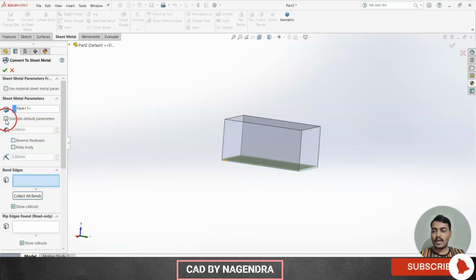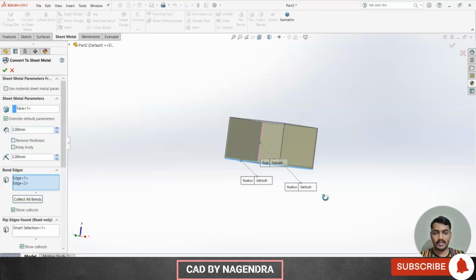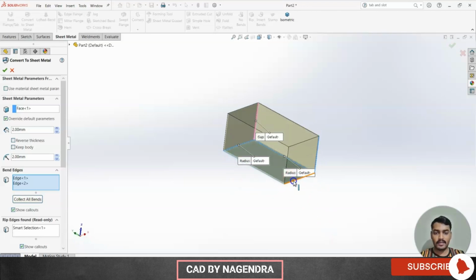Then what is the thickness we want? So I'll keep it as it is, 2 mm. Same here, reverse thickness, upside or downside we want. Then bend radius I'll keep it 2 mm. Then bend edges we need to select. This is a fixed face. With reference to that fixed face, what are the bends we want? So that bend edges, we need all these four. So just I'll select all these four edges like this.